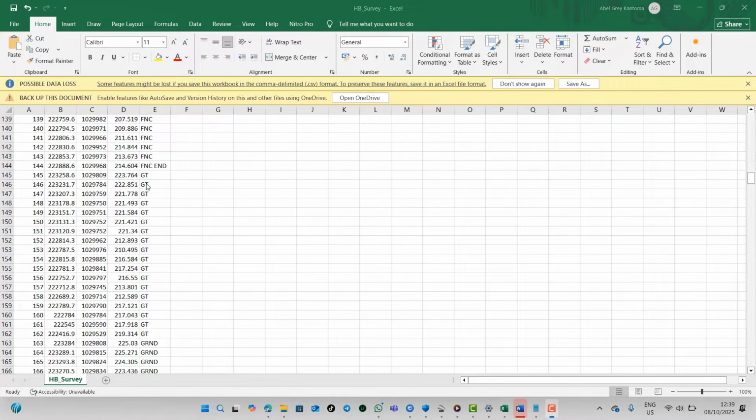It shouldn't be more than 6%, right? It shouldn't be more than 6% when it comes to the grade. It shouldn't be more than 6% along this gate area that you are seeing, right? And then you should not go more than 500 mm either below or above this gate level that you see. Any of these gates that you see shouldn't go below or above. These are very, very key important informations.